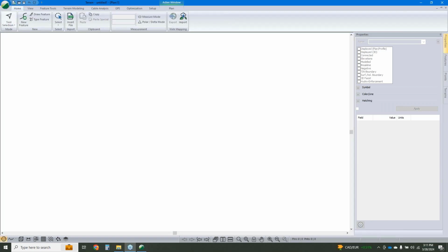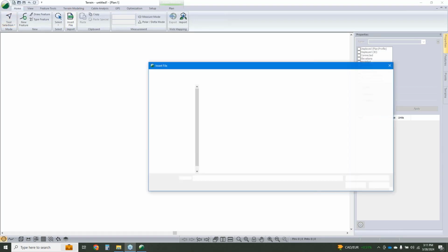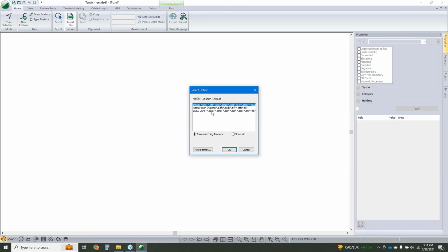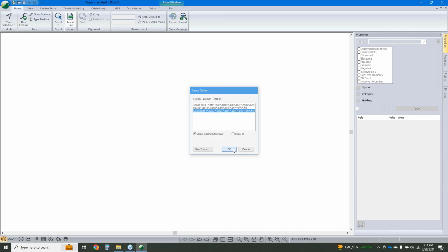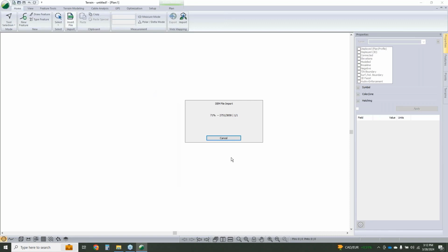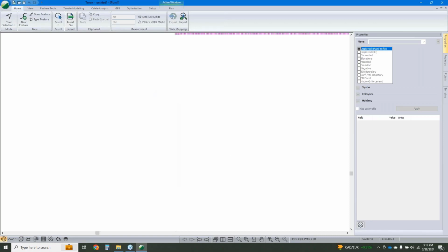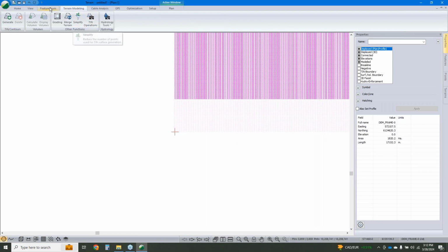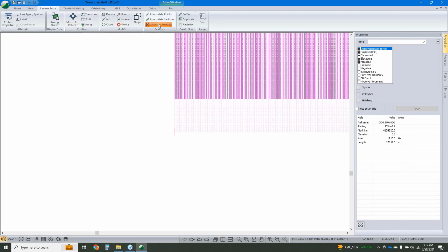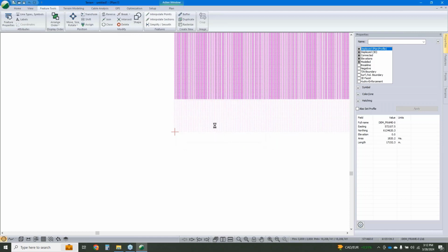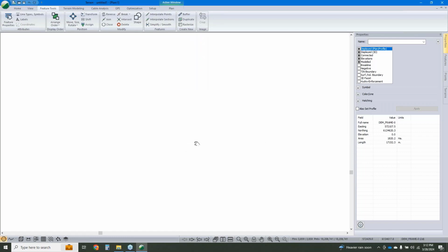Yeah, so just starting up Terrain. I'm going to click Insert, and I'm going to bring in my DEM. So it could be DEM, could be LAS. We're going to hit that. I'll hit OK. And this is a fairly large area, and I'm going to just thin down my data here a bit, just making it a little lighter without reducing my quality too much.